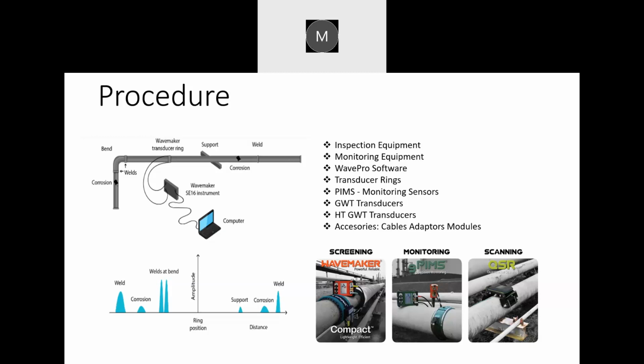Note that bulk waves cover only a small localized section of the structure, so scanning is necessary to complete an inspection of the test part. The ultrasonic guided wave covers a large area from a single probe position, and two basic guided wave excitation examples include angle beam excitation and comb excitation, illustrated in the figure above.